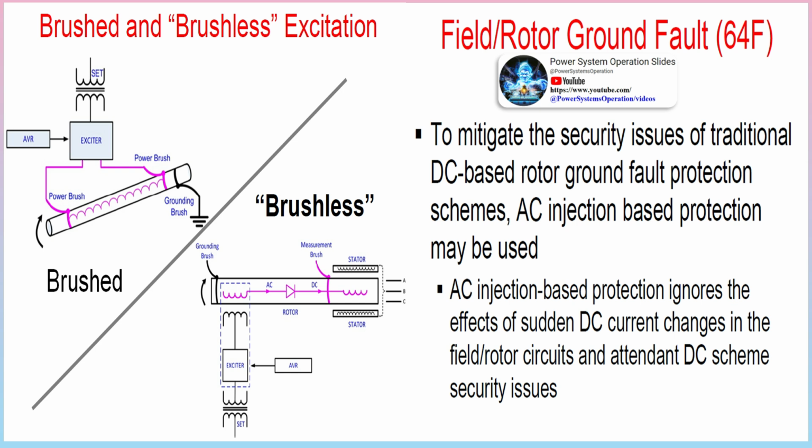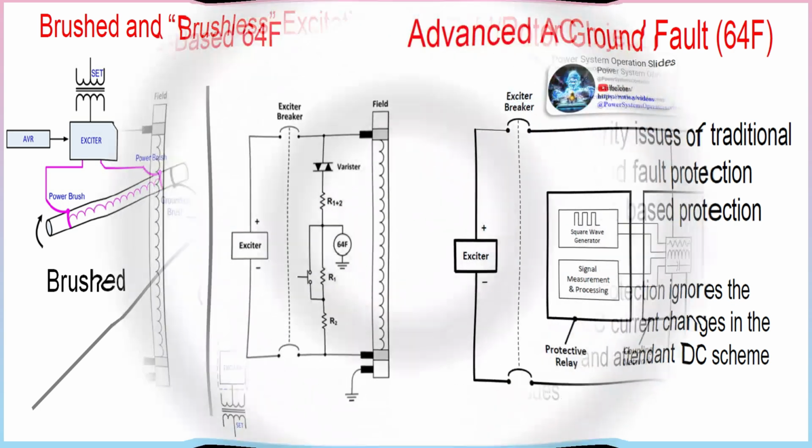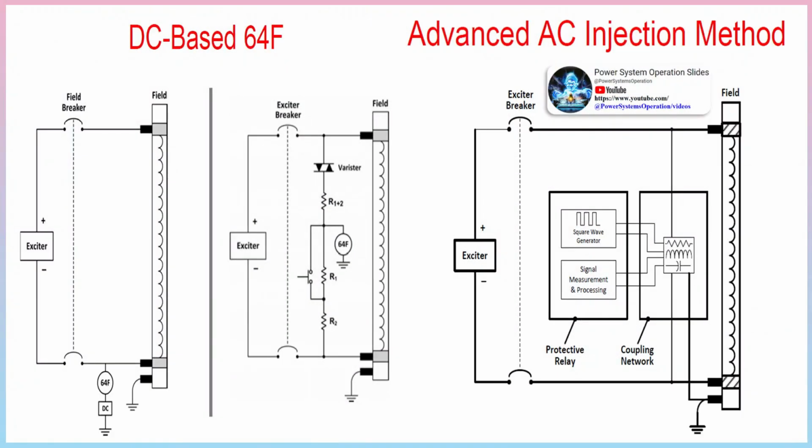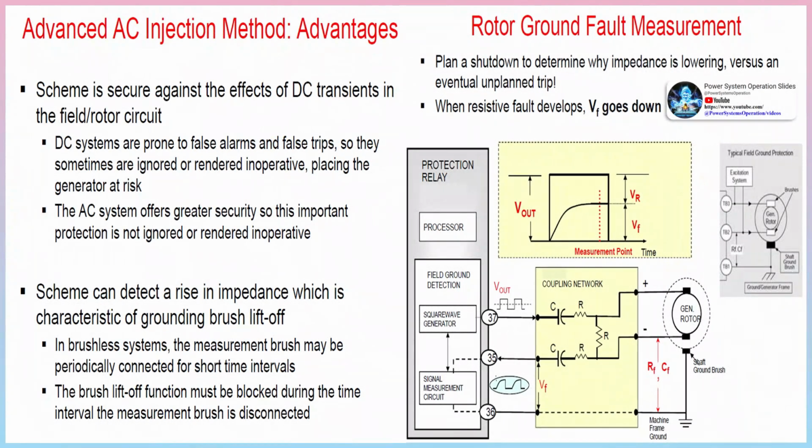Improved ground fault sensitivity, 87GD: the direction calculation is used with currents over 140 mA on both sets of CTs, 3I0 and IG. The directional element is used to improve security for heavy external phase-to-phase faults that cause saturation. When current is greater than 140 mA, the element uses the current setting and directional signal. When current is smaller than 140 mA, the element uses the current setting only. Saturation will not occur at such low current levels, so the directional signal is not required for security. This allows the element to function for internal faults without phase output current, such as with an open breaker and an internal fault source by the generator only.